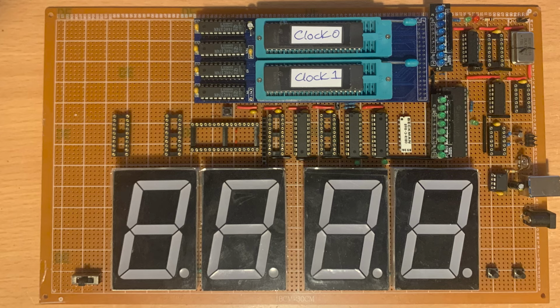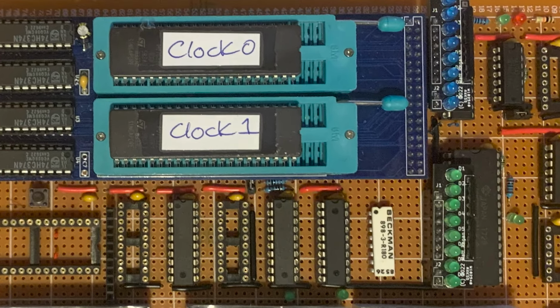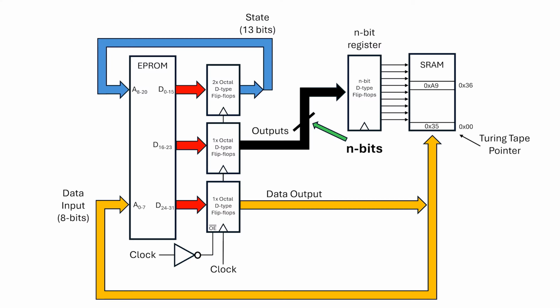We certainly can do some computations with this. It's actually the basis for the digital alarm clock that I'm building in another series. Indeed, this is the prototype for the alarm clock with the exact same architecture. But the main problem is that the memory size is limited to the size of the data bus. An 8-bit data bus gives us 256 memory locations. Now, that's plenty for an alarm clock or a calculator, but it's not enough for a full computer.